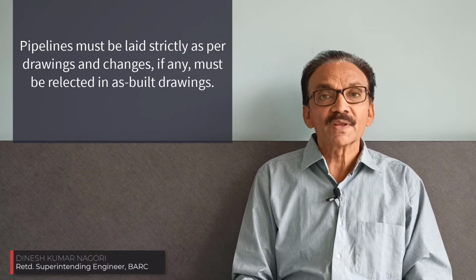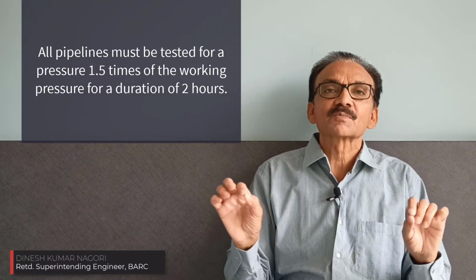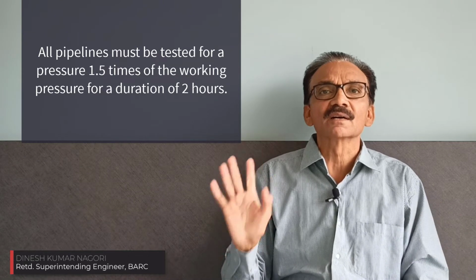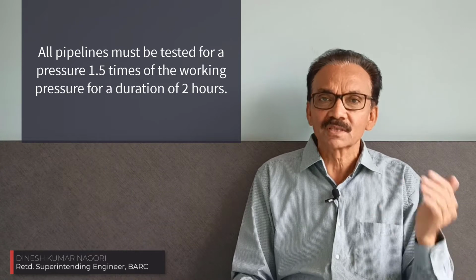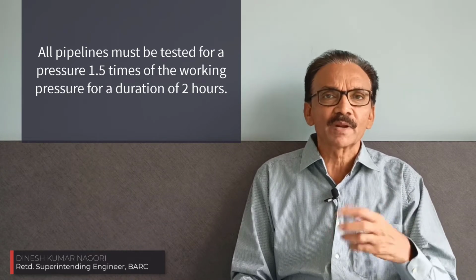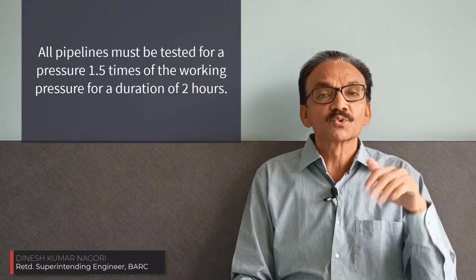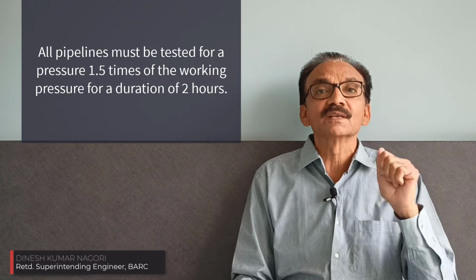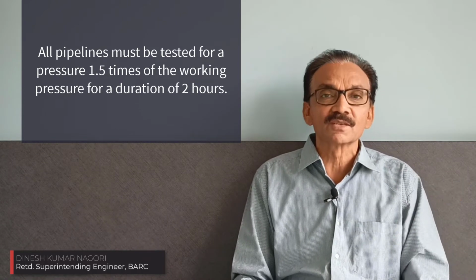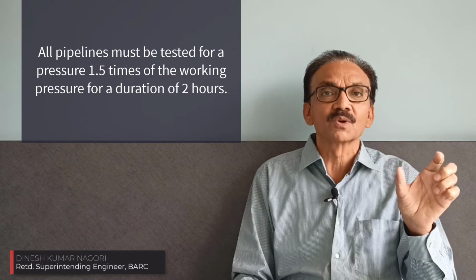Before covering up with tiles or cement or anything, that line must be tested. Generally, this water supply testing is ignored in the construction of flats, and that creates a lot of problems. Now see, the normal residential requirement of pressure is around 1.5 to 2 kg at your tap. So you should at least test the line for 1.5 times the desired pressure, so at least up to 3 kg you must test the pipeline, and you can hold the pressure for a duration of say 1 hour or 2 hours.